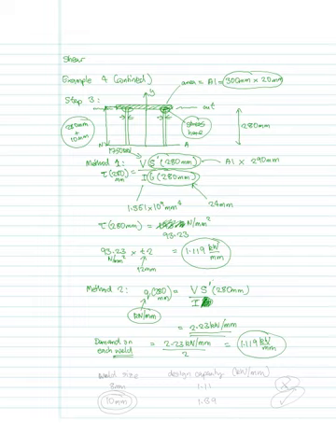So if we showed weld size, and we had 8 millimeters, and then the design capacity in kilonewtons per millimeter, we saw that for 8 it was 1.11. 1.11 is smaller than 1.119, therefore an 8 millimeter weld would not work, and if you designed an 8 millimeter weld, the weld would fail.